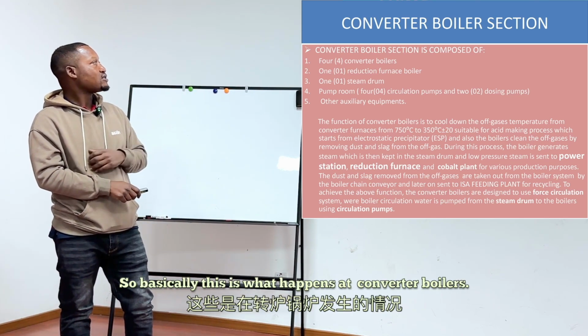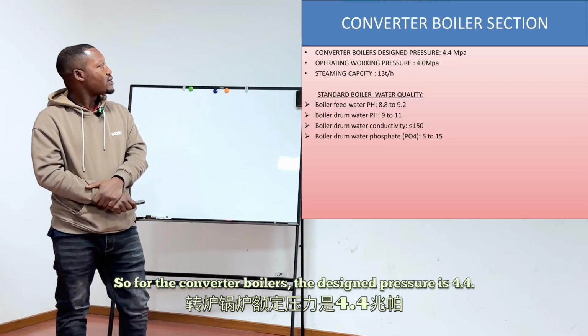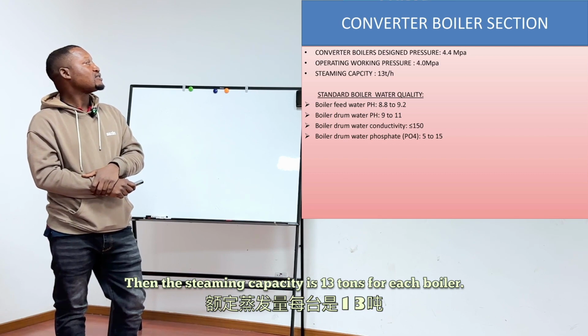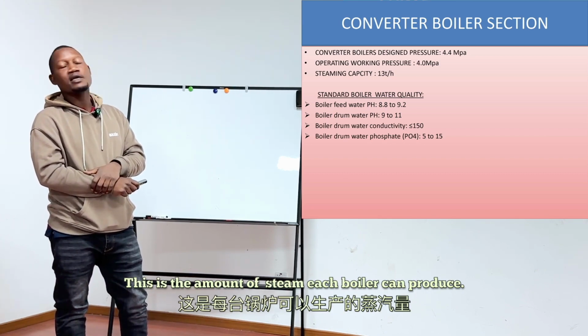So basically, this is what happens at the converter boilers. For the converter boilers, the design pressure is 4.4. The operating working pressure is 4.0. The steaming capacity is 13 tons for each boiler. This is the amount of steam each boiler can produce.